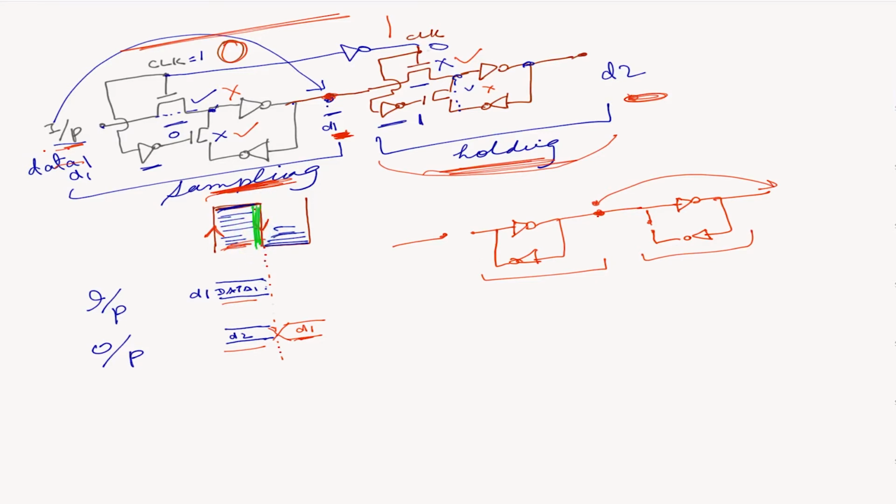First, because if you change your input here, like let's say you put D3, now this side will take it, and then the output will immediately take D3, while we wanted to keep D1. So this time before the sensitive edge of the flip-flop, where we need to keep the input data stable, is called setup time.